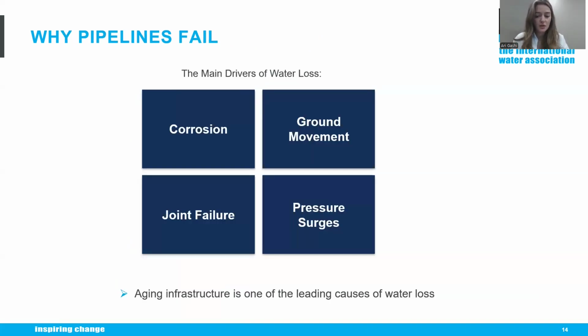So why do pressure pipelines, or pipelines in general, fail? In reality, there's usually no single reason. Instead, several factors often interact over many years. For example, for metallic pipelines, corrosion remains one of the most common causes. Internal corrosion gradually reduces the wall thickness, while external corrosion attacks the pipe from the outside. Joint failures are another common issue; ground settlement, installation tolerances, or aging sealing materials can all cause joints to lose their integrity over time.